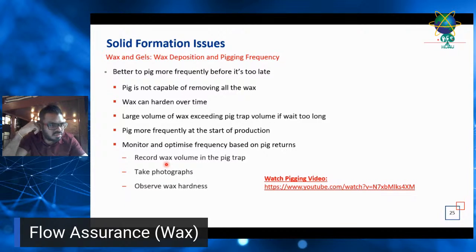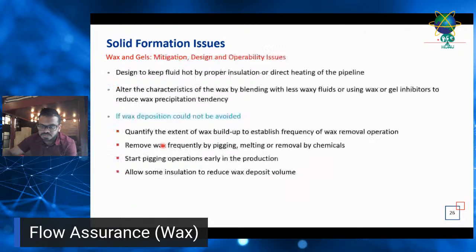We need a lot of equations involved for the cold finger data. We need to convert the rotational flow to pipeline flow, to axial flow, and only then can we use that to tune the wax model. Whereas if you have the luxury of getting this data from operation, that would be much better in terms of tuning the model, especially the wax deposition model.